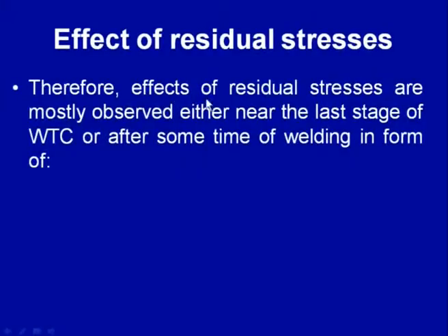Some of these effects we will be discussing in detail, like the first one, the effect of the residual stresses. They are mostly observed near the last stage of the weld thermal cycle or after some time of the weld. This is because the residual stress magnitude is found maximum only after cooling down the entire system to room temperature. Once the maximum magnitude of the residual stress is developed, they will have the maximum effect on the performance of the weld joint in different ways.